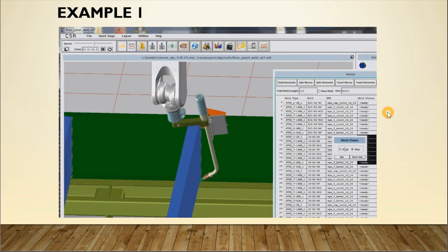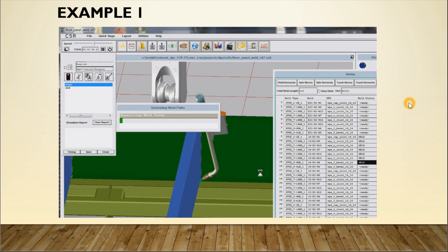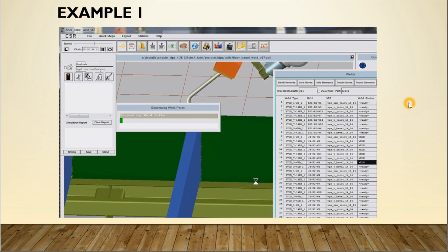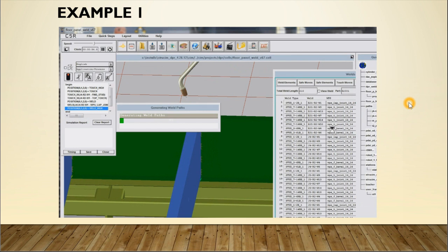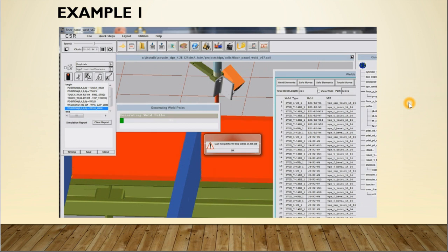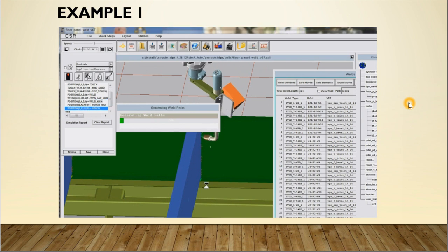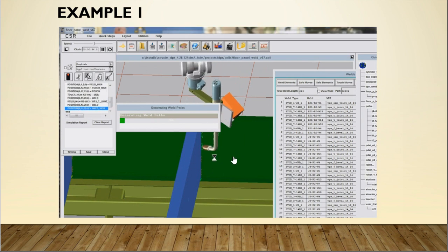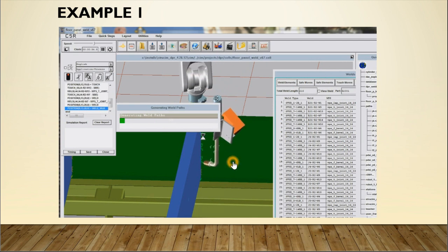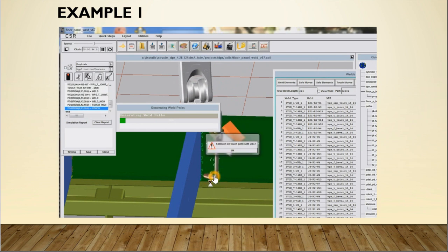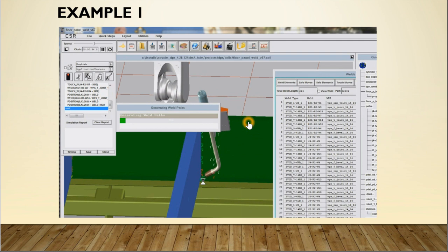Alright, here's an example that I kind of alluded to. So here's us programming it. We select these welds, these 6 welds that we want to program. Now sometimes because of collisions you can't program the welds, and in this case we have these four vertical brown welds, and they're all treated the same, and so they said, well, we don't want to try to automatically adapt. We want to actually set the push and the work angle. So we said, well, we just can't reach it because it's too close to the flange on the bottom and too close to the flange on the top.